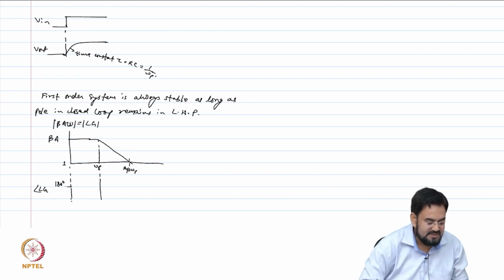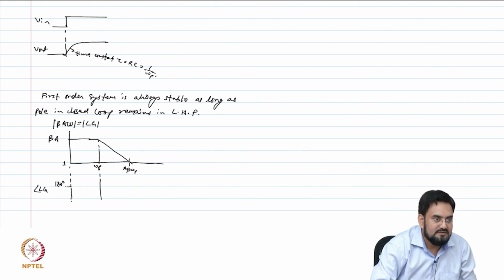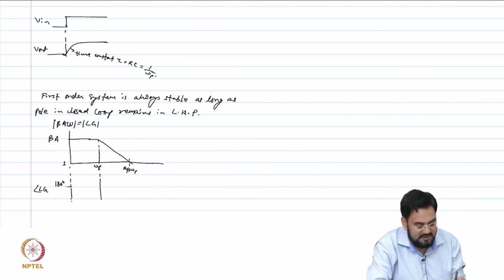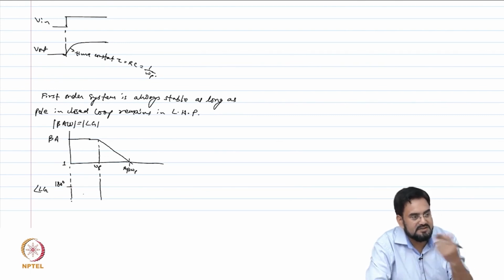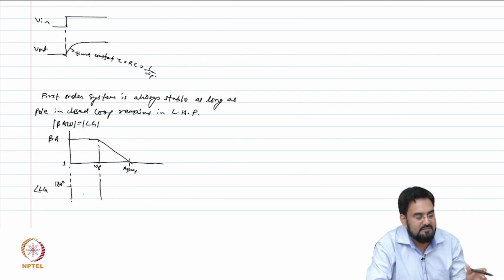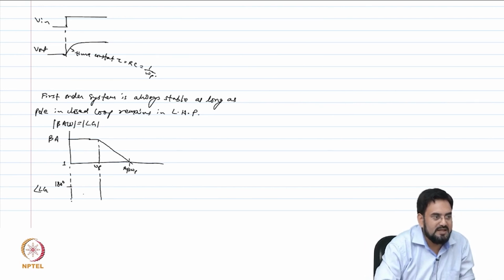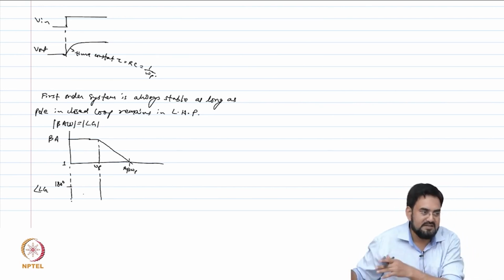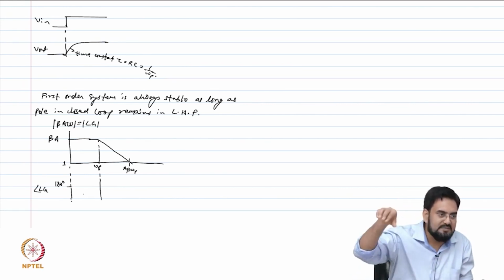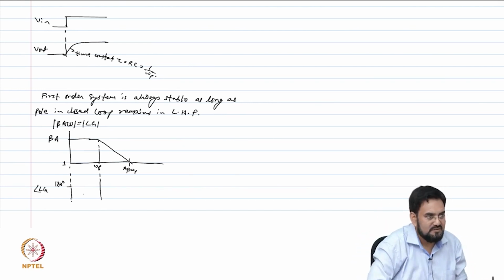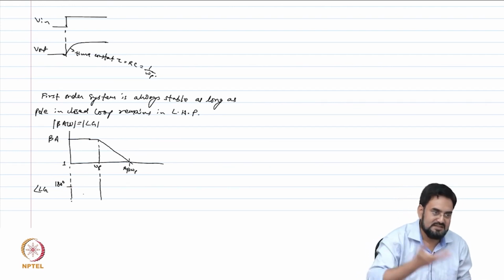In some cases, some people start with minus 180 in order to show that a pole has a negative phase. If you start from 180, you are going from 180 towards 0. If you start from minus 180, then you are going towards minus 360. Just show that your phase is moving in the same direction. Even in the simulator you might see it start from minus 180 instead of 180, but it doesn't make any difference. Ultimately 360 is the same as 0 degrees.